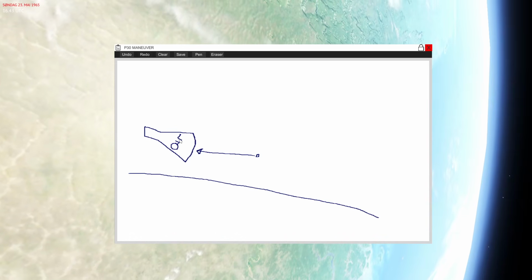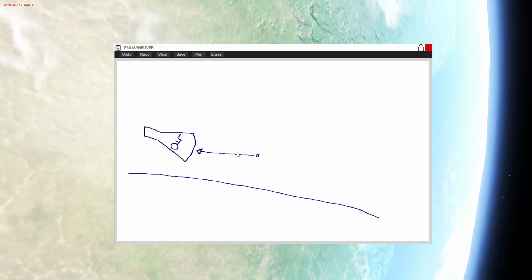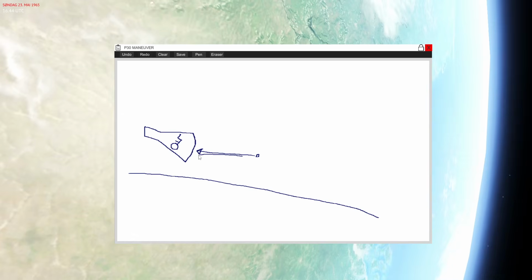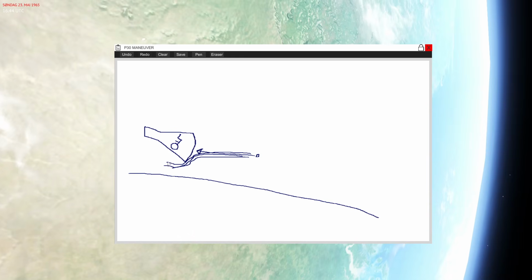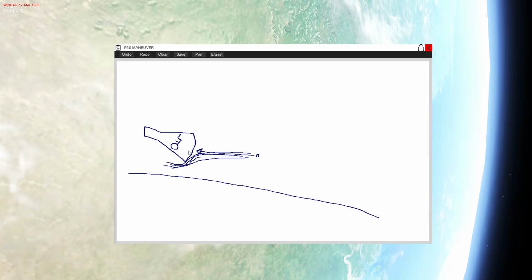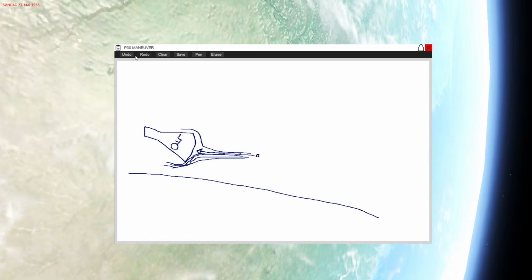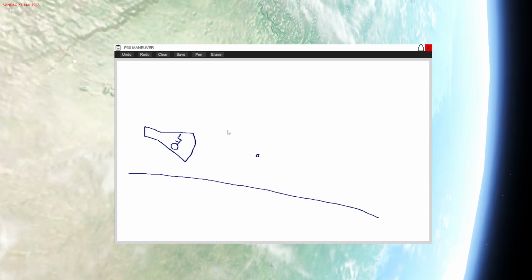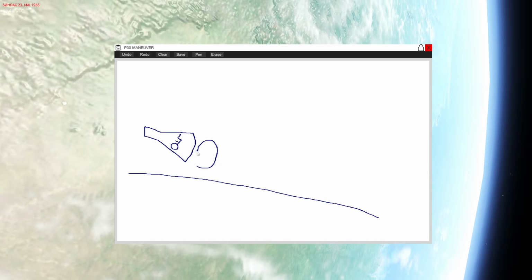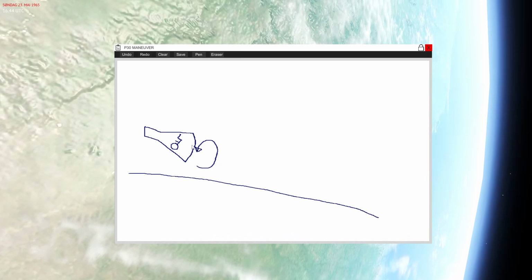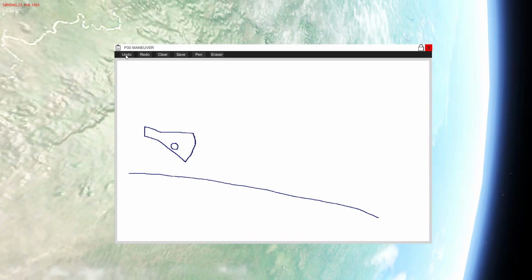Since we now have a tilt with regard to the center of gravity, more air is going to go one way because there's a tilt to the heat shield. So the heat shield starts to act like a wing. Using roll, we can roll the spacecraft around to decide which direction this wing is pointing.